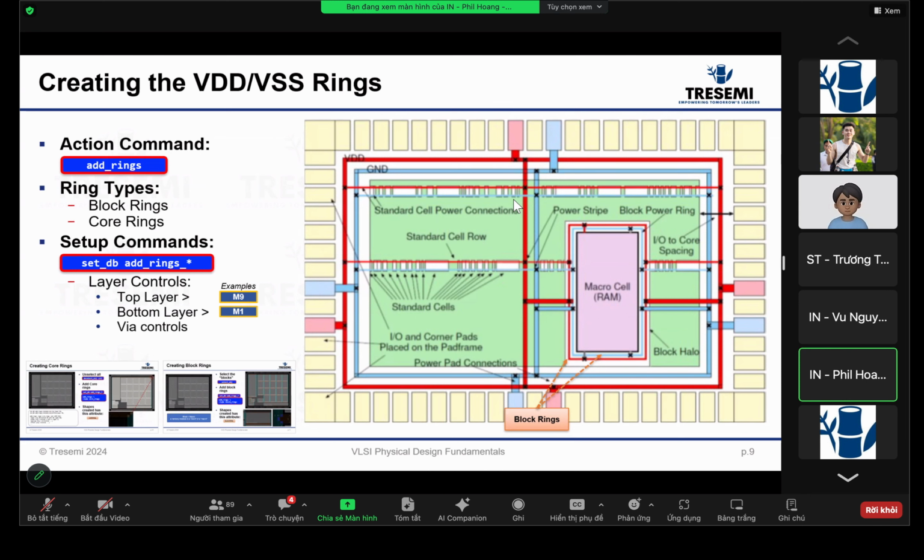But for a special interface like DDR, the interface to external DRAM, this IO pad can operate at very high frequency, like 2.4 gigahertz or higher. So the voltage has a significant contribution to the overall power consumption of the IO pad, and so the power consumption of the system. The new type IO pad like LPDDR4 is 1.1 volt nominal, but LPDDR4X is 0.6. That's just one example.